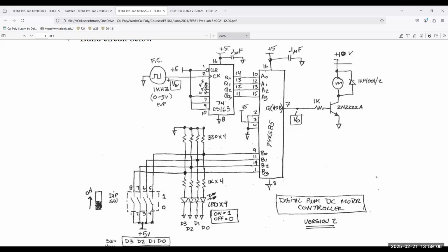So we did the analog comparator. This one right here, the long rectangular chip, the 7485. The 7485 is a digital comparator. It compares two 4-bit digital inputs, A and B. The B input that you see is manually set either to plus 5 volts or to 0 volts. And it's set through this DIP switch. Dual inline pin has 4 switches in one. It's a small black switch with a white slider on it in your lab kits.